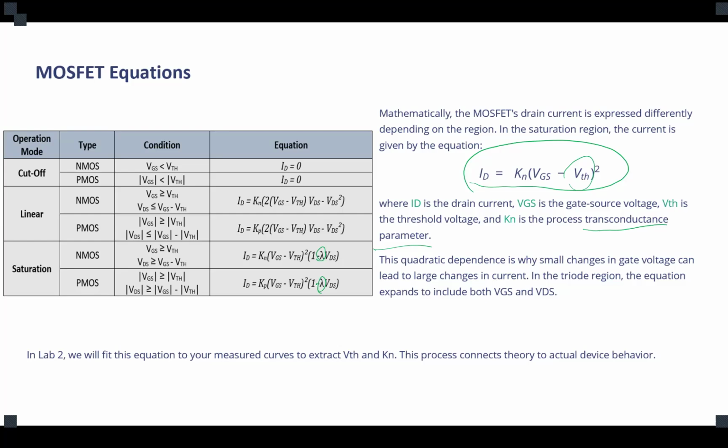You start to go up, increase the voltage until you see that the MOSFET is turned on. That voltage will be the threshold. Are we good? Now, after that, you are gonna connect an ammeter in series with your drain.